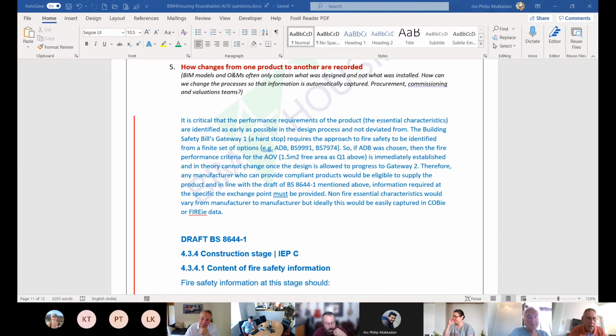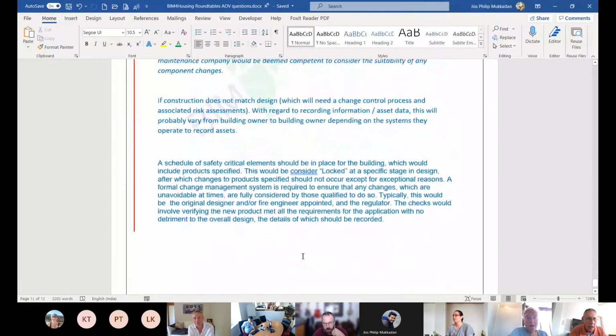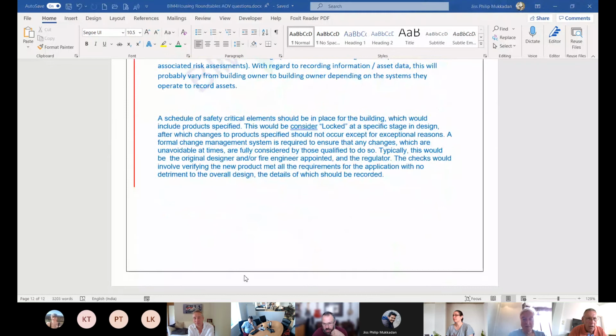I mean, there's a multitude of things. We've had things with balconies, well, it's actually more like decks, where the wrong installation products were put in. For instance, polystyrene, which the industry will say you need to encapsulate. You put polystyrene with a timber deck over the top, you create a situation where it's very easy to start quite a substantial fire. And then products around it which would normally pass fire tests don't, because of the size of the fire that it's exposed to.